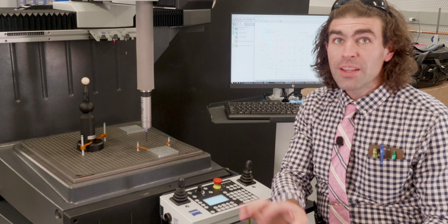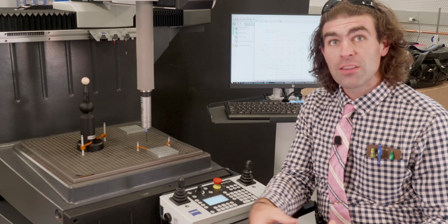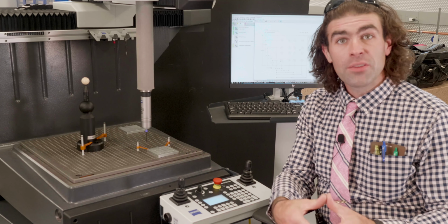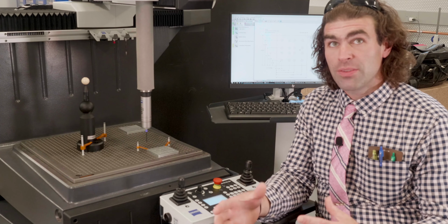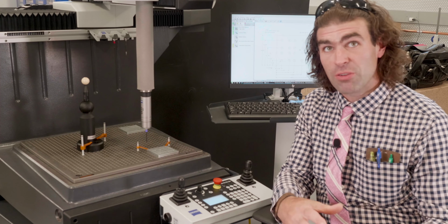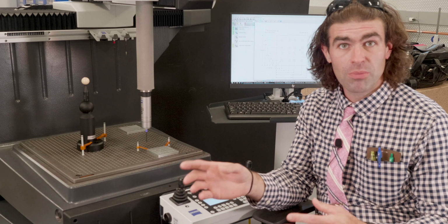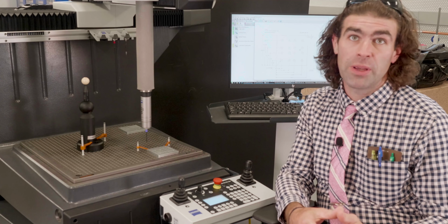So a feature is just a physical portion of the part that you're going to measure. The characteristic is what's on the drawing. So you could find a circle on the part, but the characteristic would be the diameter. Now there's different ways to get the characteristics. Sometimes we can report them from the feature, so we don't have to do a bunch of extra clicking. I'll show you both ways to do it.